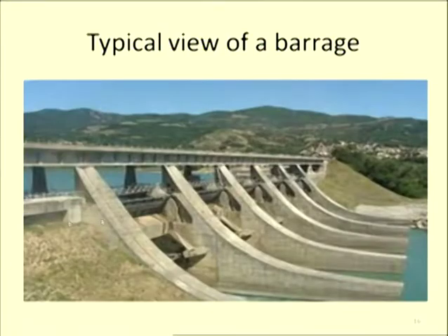If we look at this valley and channel, all these points are where the gates are fitted in, these structures standing tall with gates fitted in. So all these are piers here, here, here, and at the end there would be the abutment. This is the rock where finally the load is carried into the sides of the valley, and these piers carry the load to the bottom foundation.